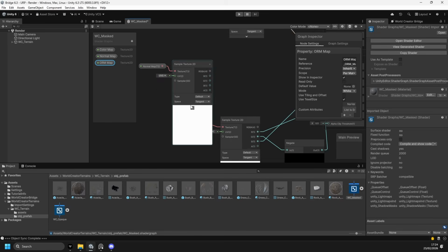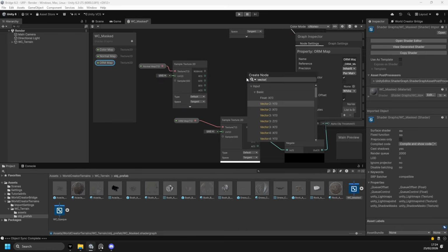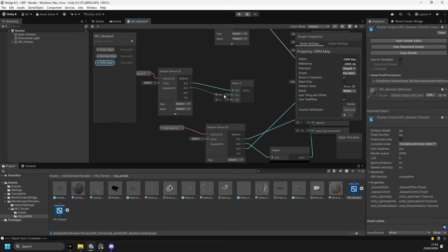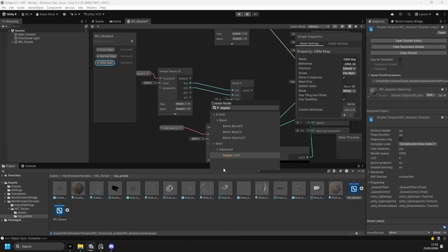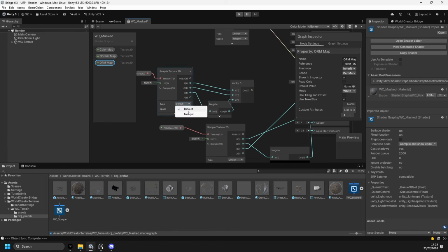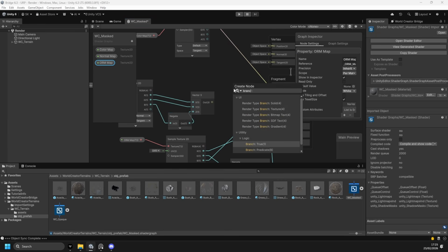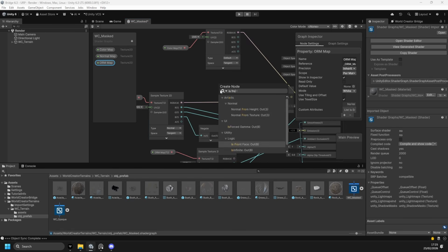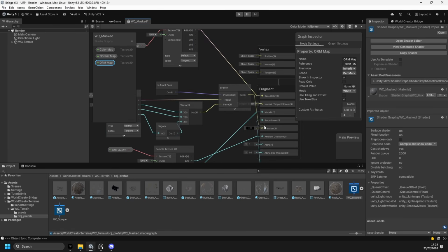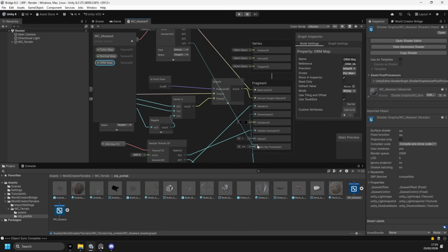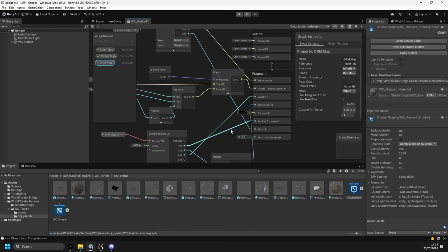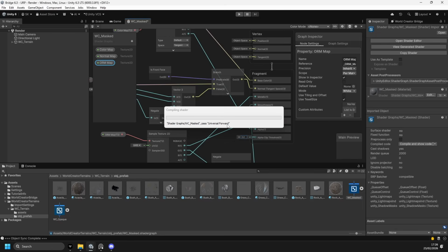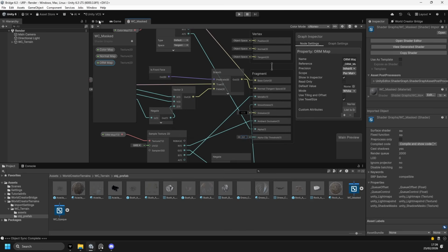The thing we now do differently is that we add an invert to our normal map up axis when we're on the back face, so that in that case our normal map works correctly. Lastly, we connect the alpha channel of our color map to the opacity output and set the threshold to 0.1, so we get as much area of our mask as possible. With our graph saved, let's apply it to our scene.